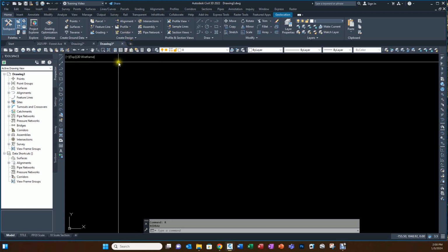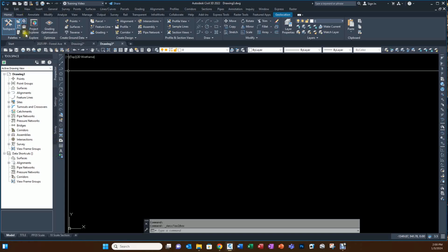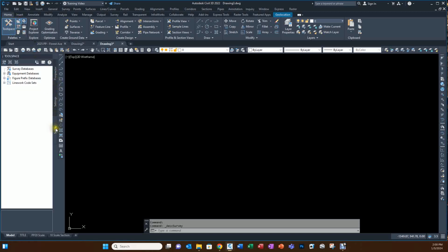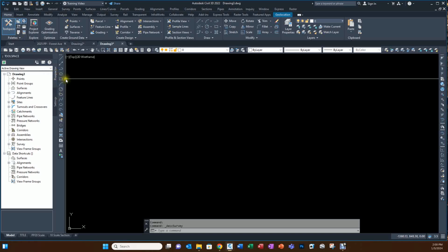On top of that, we have this thing called a tool space, and you can turn off tool space from the home ribbon bar. And tool space has different tabs on it here based on these four settings here. So this is toolbox. If I don't want to see toolbox, I can turn that off. Or if I don't want to see survey, I can turn that off. And now the prospector and settings tabs are the only ones shown. If I want the survey back again, I select that one and it's back again. The ones we will really continue on is the settings and the prospector.